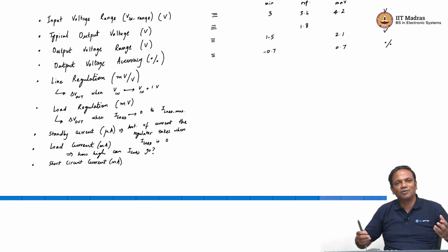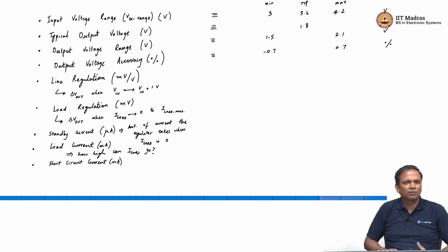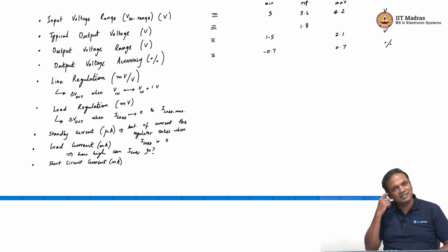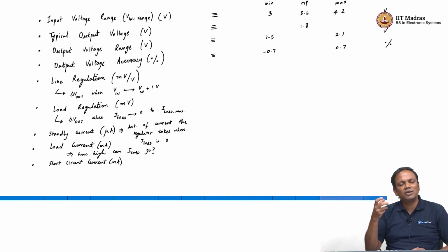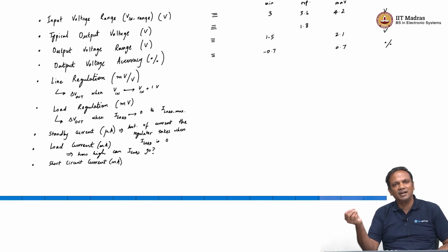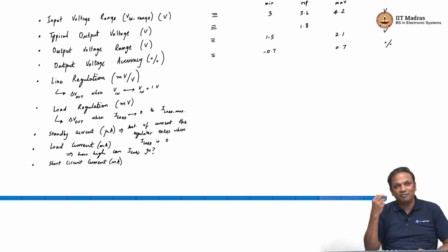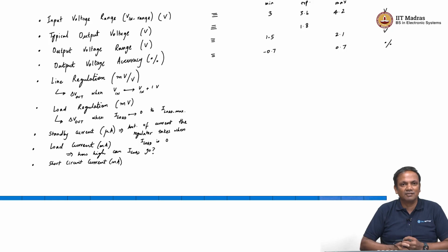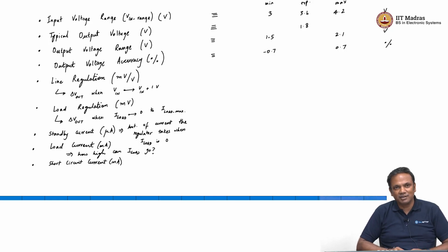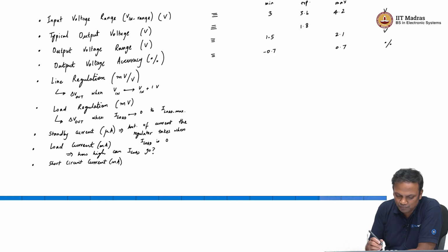Understanding the world of mass manufacturing is very important for an embedded system engineer. So, if you are looking to ship millions of units a year, if you are building a product that will ship in the millions of units per year, then it is very important as the person architecting that system to be confident that we are not going to have a lot of loss in yield because of the way the design was done. Design needs to comprehend variation in components, the distribution of that variation, and make sure that we will still get a very good manufacturing yield when we go to large volume.